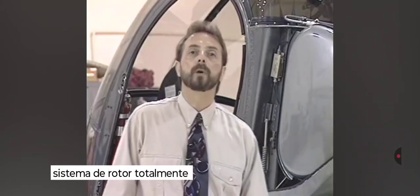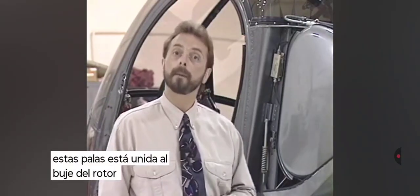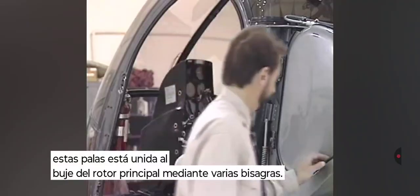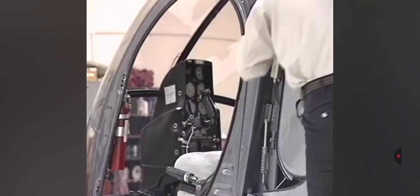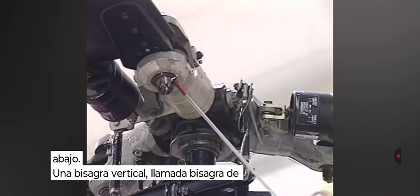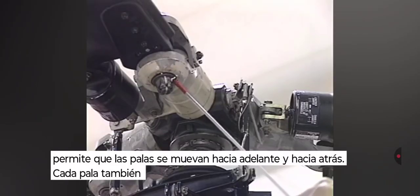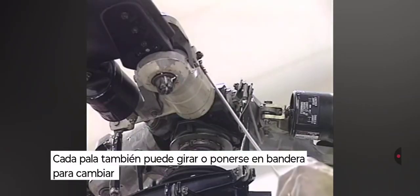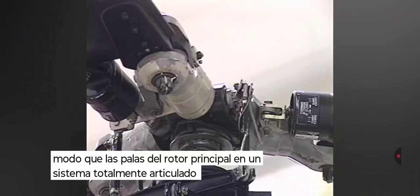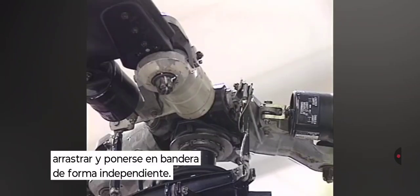The fully articulated rotor system consists of three or more blades. Each of these blades is attached to the main rotor hub by a variety of hinges. A horizontal hinge called the flapping hinge allows the blade to move up and down. A vertical hinge called the drag hinge allows the blades to move back and forth. Each blade can also twist or feather in order to change blade pitch angle. So the main rotor blades in a fully articulated system can flap, drag, and feather independently.